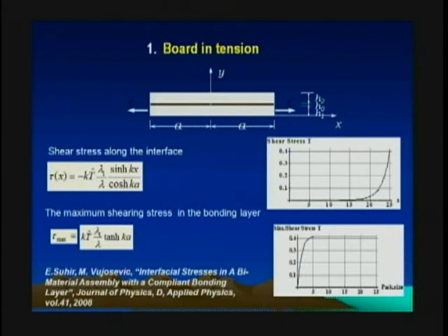The thing is that in the drop tests, the printed circuit board is subjected to tension. It's also subjected to bending, but we already knew that the tension is huge, and the more severe the loading is, the lesser role is played by bending, and the greater role is played by tension.